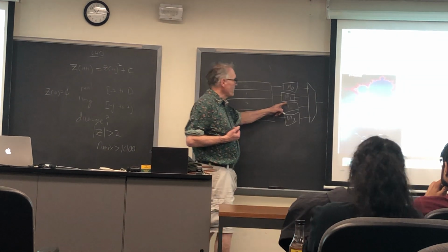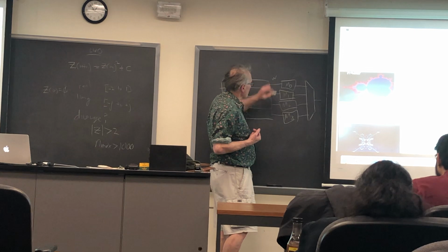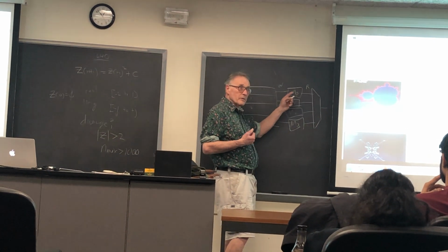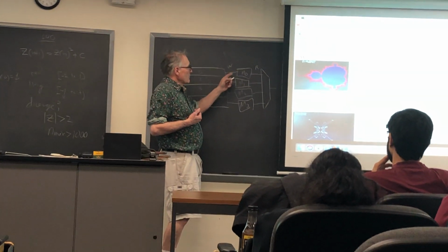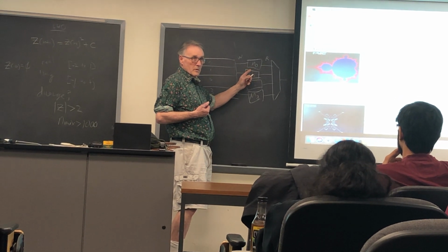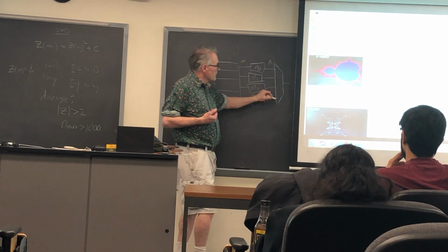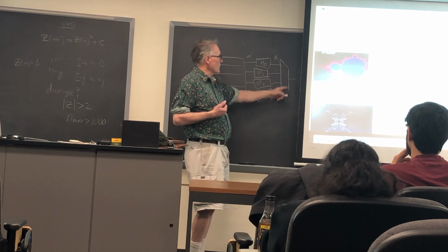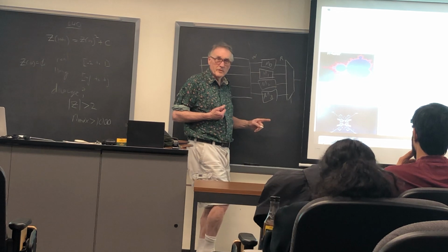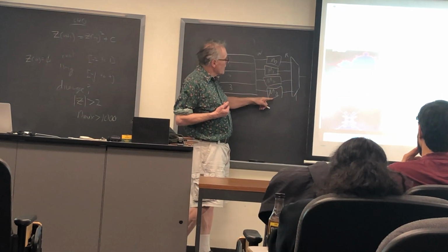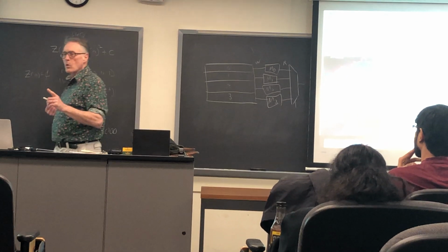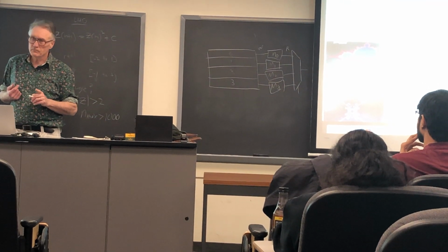So it's dual ported memory. This port is a write port, this port is a read port. There's no conflict between read and write because the memory is truly dual ported. So you have to mux the VGA controller on this side to know which block to read from, so you have to use a custom controller. But this means that you can write with absolutely no memory conflicts.